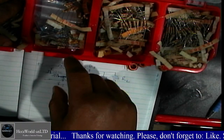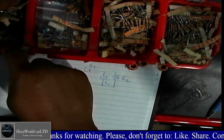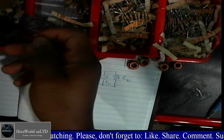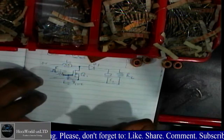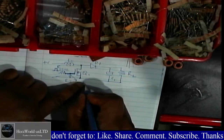Are we going to look for 10K, 10 kilo ohm, or what did we say here? The color code for 10 kilo ohms is going to be brown, black, orange.